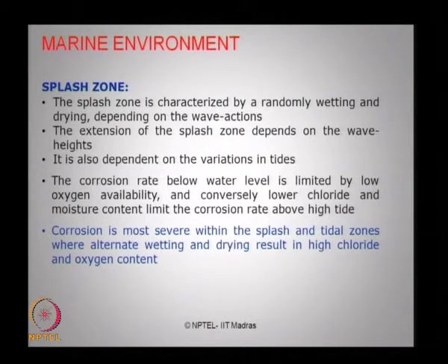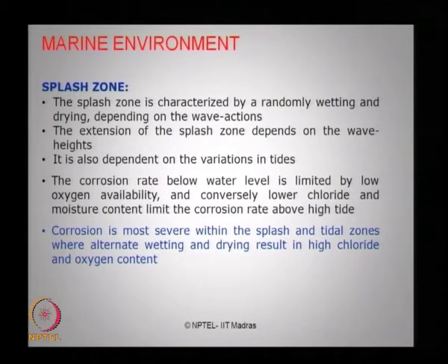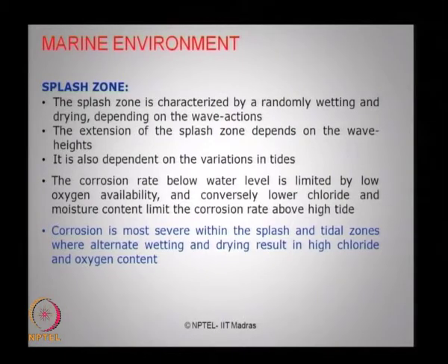The corrosion rate below the water level is limited by low oxygen availability, and conversely lower chloride and moisture content limits the corrosion rate above the high tide zones. Ladies and gentlemen, therefore, corrosion is most severe within the splash zone and the tidal zone where alternate drying and wetting takes place. This results in high chloride and oxygen concentration, which is one of the primary factors which activates corrosion in reinforced concrete, especially in concrete as a construction material for ocean structures.